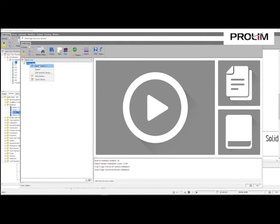So now if I just right click here, I can go to new symbol, and I'm just going to start cranking in these symbols. I'm going to either pull in the DXF of my old symbols or go in and create my new symbols that I need. Or I can actually copy existing symbols from the IEC that I do need, and I'm just going to create a one-stop shop for all of the symbols that I use on a daily basis. This is where you do that, and that's, again, very simply how you do that.